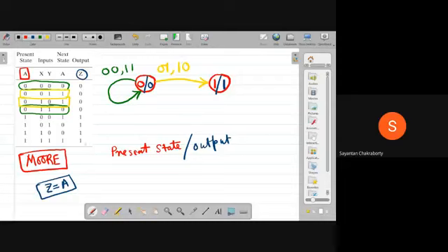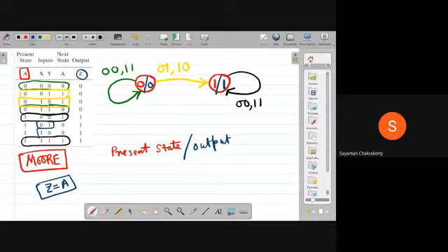Now it is at state 1, 1. See? So if it is at state 1, 1, let us see where it doesn't change its state. When the input is 0, 0, it doesn't change its state, and when the input is 1, 1. So clearly, these will be the two input conditions for which it remains in the same state. And then when it does change the state, they are 1, 0 and 0, 1. So this is the complete state diagram following this Moore model. Now understood? Okay?